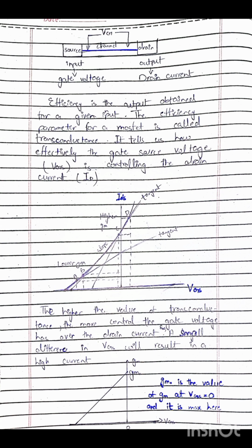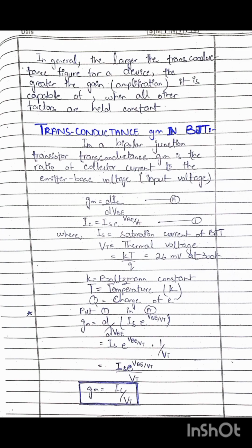The transconductance curve is nonlinear, showing that changes in VGS do not directly result in proportional changes in drain current, highlighting the complex relationship between the input voltage and output current in these devices. Different regions on the curve, such as the cutoff region, ohmic region, saturation region, and breakdown region, represent distinct operating conditions of the transistor, providing valuable information for circuit design and analysis.